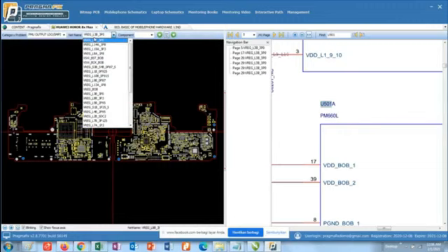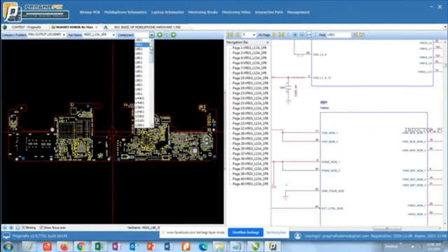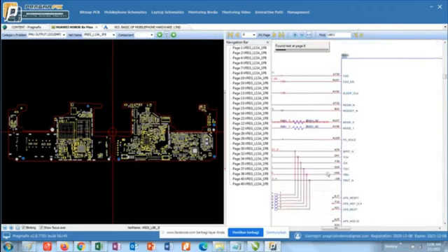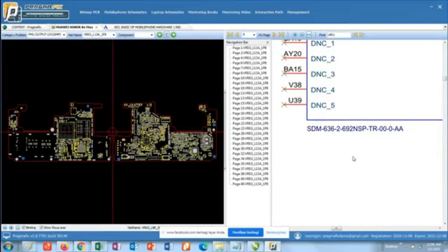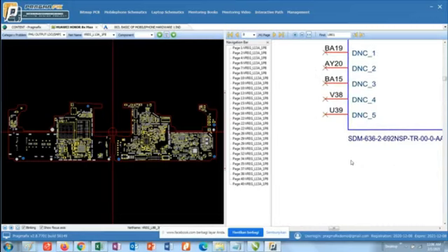We just need to make sure the voltage from the power management unit U501 or U201, that is PM660 and PM660L, was already available. Well, the first three things are for the AP, the application processor. The processor in this case means U800.